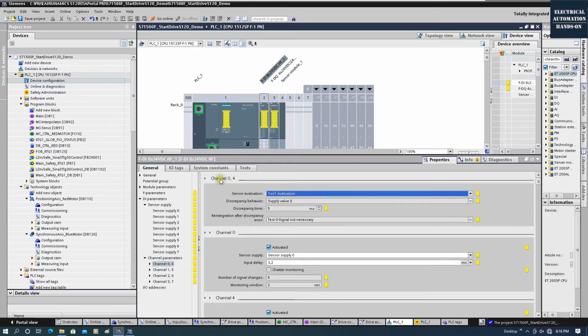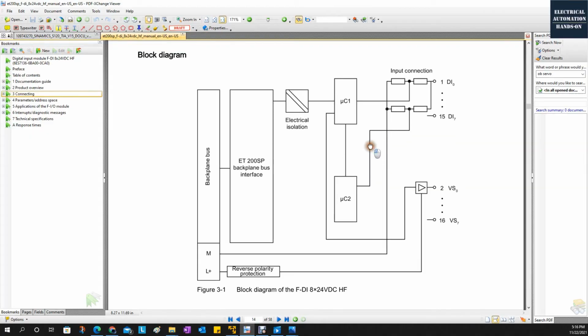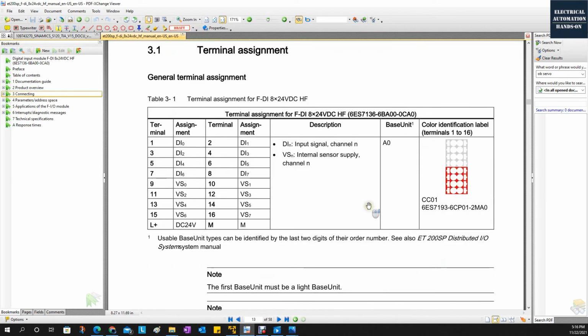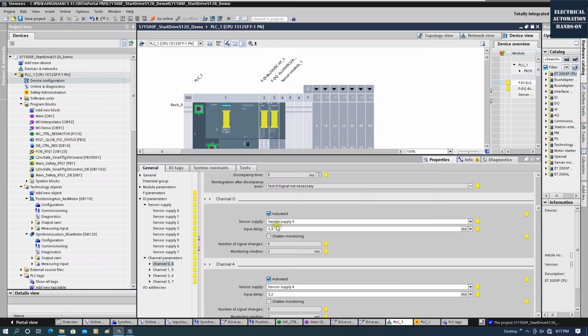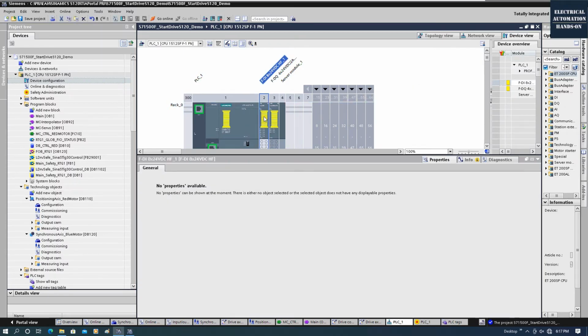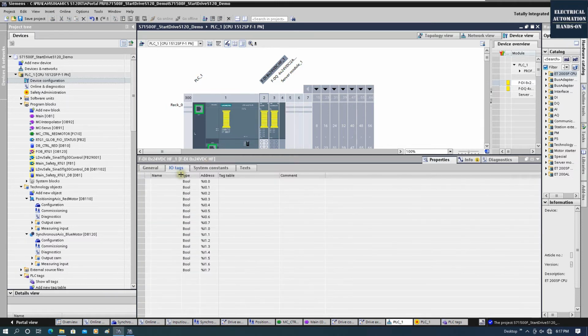I will only use the channel 0. Okay, this is this safety module. So I'm using the input 0. It has 8 channels. So I'm using the VS0. This is my safety button circuit going back. So as we can see, this is the input channel. I'm using one switch, connected from number 9 to 1, like this style. On, we will give an enable. I configure this.